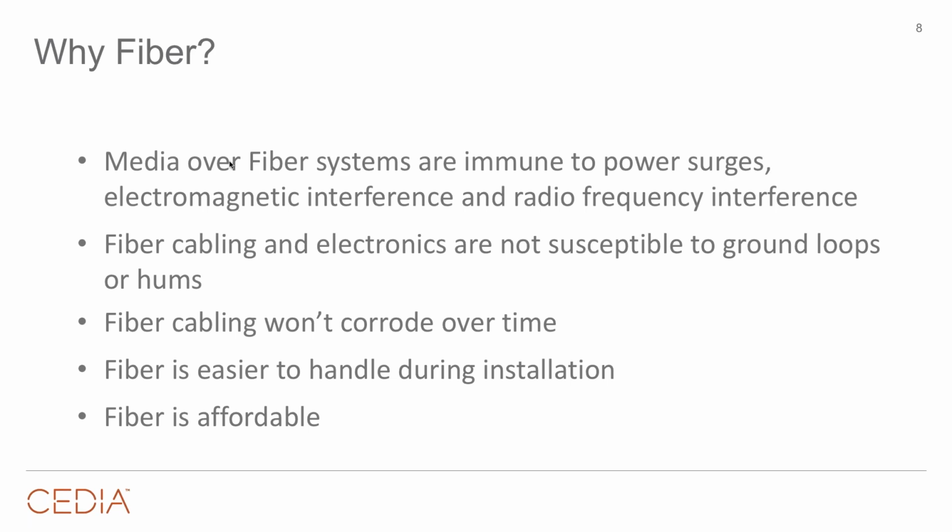That's why you'll have an installation where, hey, everything's working great. And then 10 days later, you get a call from the homeowner and they say, hey, look, I don't have any picture on this display. That's often from crosstalk knocking out the individual signals because our cables are being interfered with. Okay? Fiber is immune to that. That's why we see it in government. That's why we see it in medical applications. That's why we can use it in these very sensitive, big installations in our CI world and in our professional AV world. Fiber is an ideal mechanism for that.